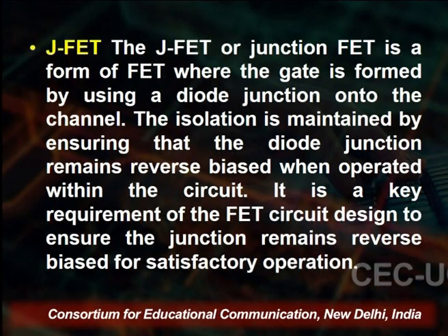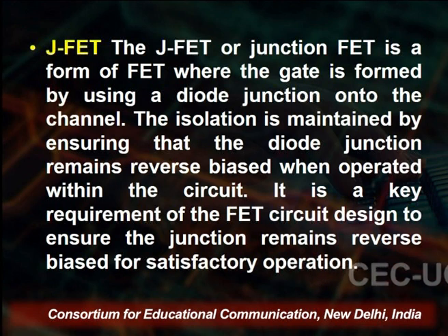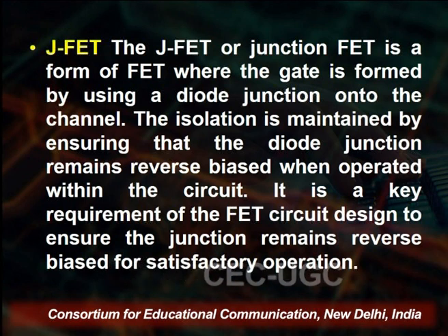Next is the JFET, where J stands for junction. The junction FET is a form of FET where the gate is formed by using a diode junction in the channel. So the isolation is maintained by ensuring that the diode junction remains reverse biased when operated within the circuit.